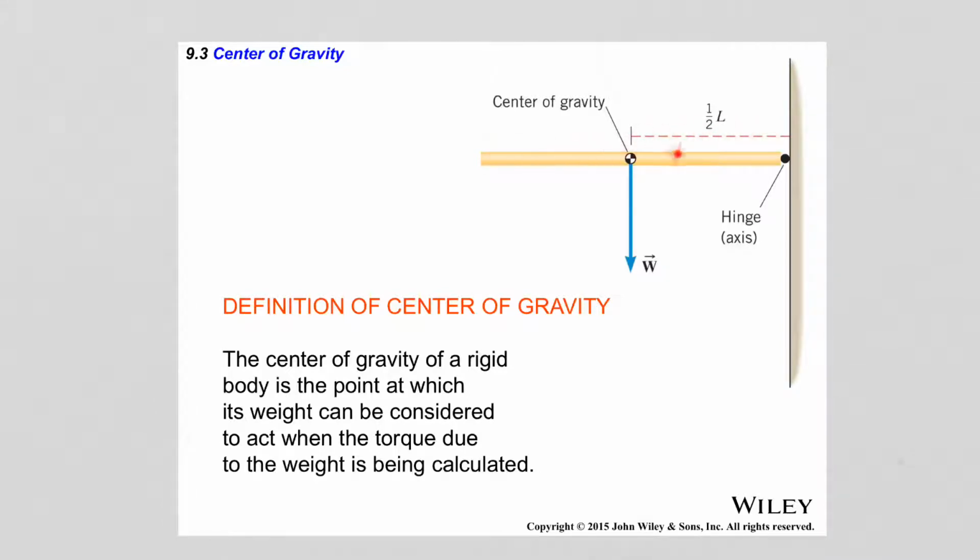This only is true, meaning the position of the center of gravity right in between the two ends, when an object is uniform in how the mass is distributed inside it. If the mass is distributed in a way that is not uniform, for example, imagine a baseball bat, then the center of gravity will be shifted towards the heavier end. For our purposes, in general, we are going to consider nice symmetric objects for which the center of gravity will be focused at the geometric center of the object.